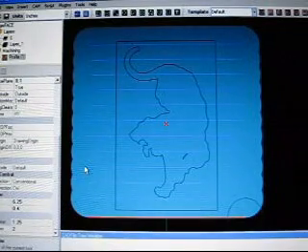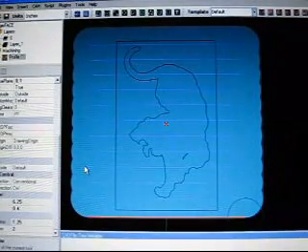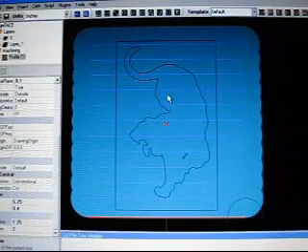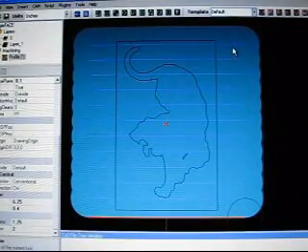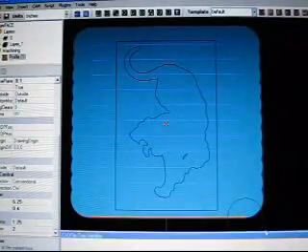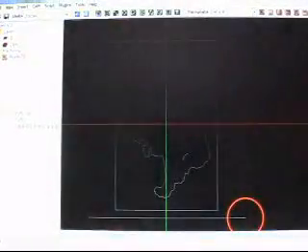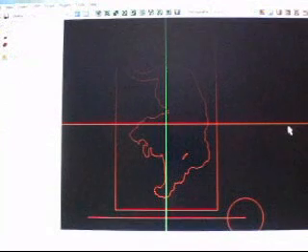So that's about it as far as facing is concerned. You do want to watch yourself when you're facing parts off. You do want to not plunge. I can't stress this any more than I already have. A big fat mill, you don't want to plunge it directly into your part.